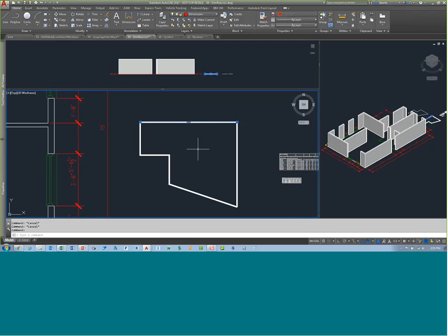And then, since you already have it subobject selected like this, you can hit the delete key, and it will get rid of that one particular portion. That system variable is called legacy control pick, and you can set it to either 0 or 2. The default is 2.